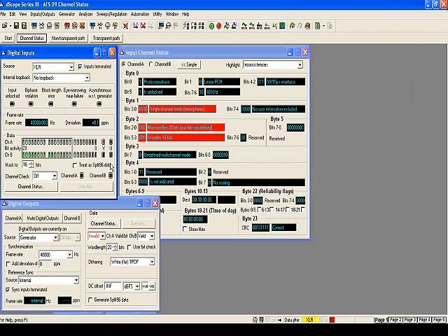So everybody's pointing their fingers at this piece of equipment that muted, and as it turned out, they pulled out the DSA-1, put it into the signal path, and discovered that there were invalid validity bits set on the piece prior to the evaluation piece in the chain. So the only manufacturer that was complying with the spec was actually muting it.